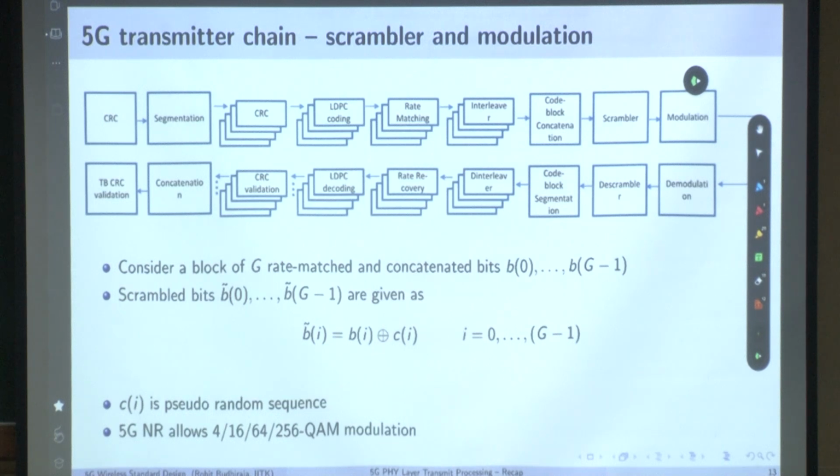Now what happens at the receiver? You will down convert this RF signal. Then what follows after this RF down converter is the ADC, analog to digital converter, because you have to do the reverse processing. Once it gives you that, there are a few additional modules.